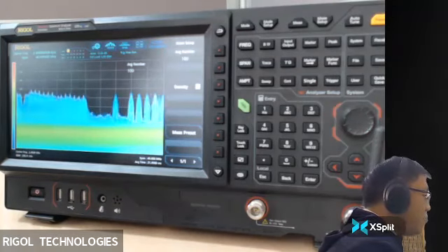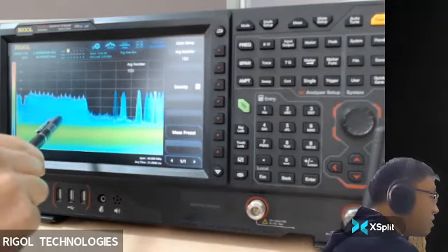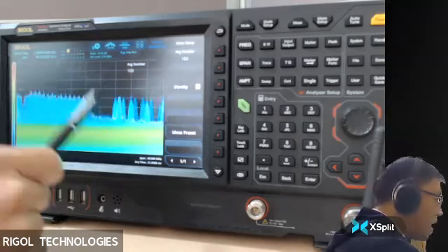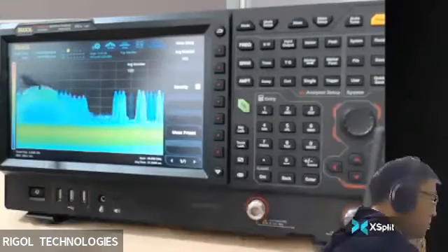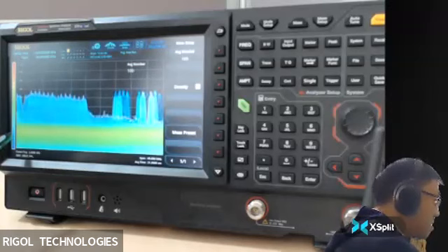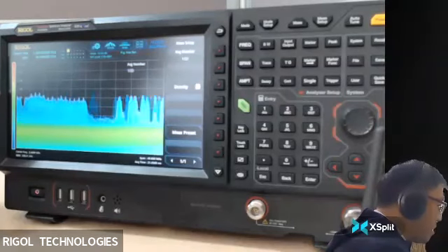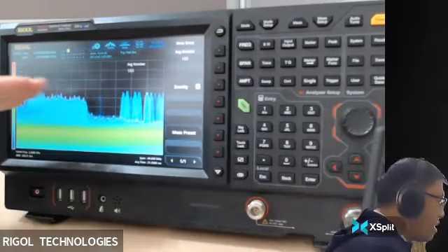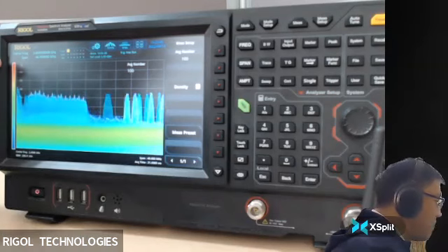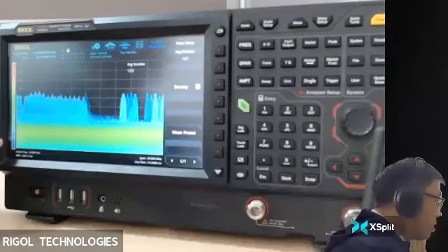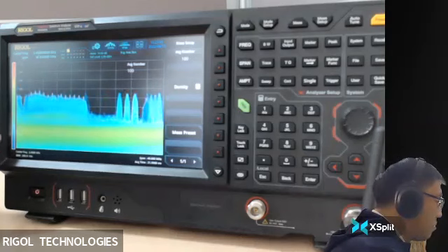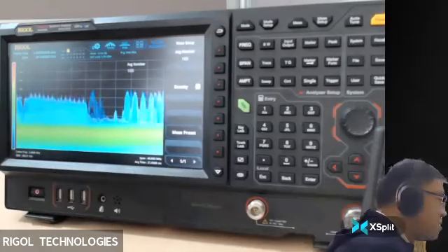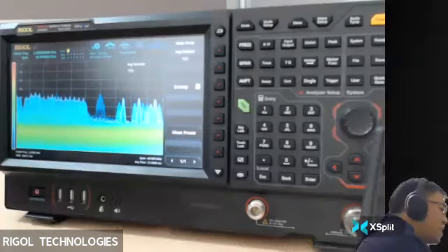So have the density 1, you can show the advantages of the real-time spectrum mode, because all the hopping signals can be shown in real time on the display here. It is the color grade distribution. If the color is deeper, approaching the red, that means the probability density is higher at some place. And if the color is approaching the lower side, the blue one, that means the probability density is very low, that means the probability density is small.